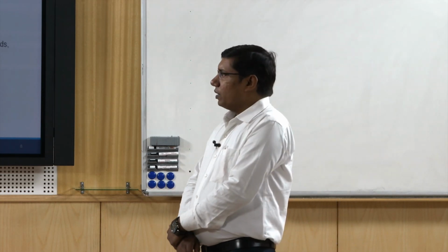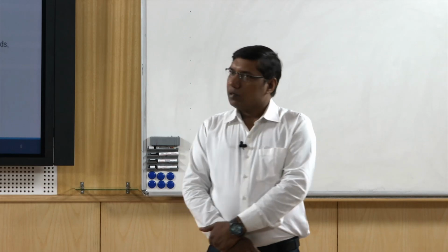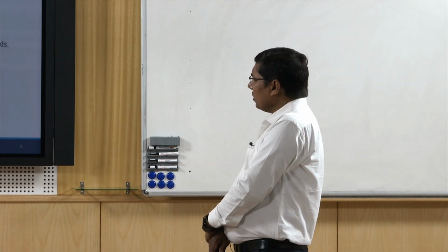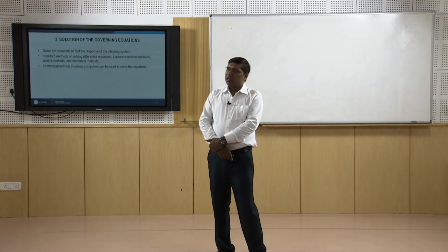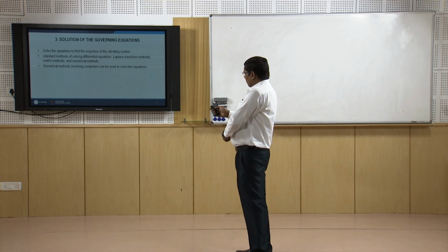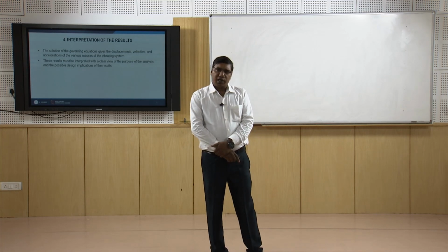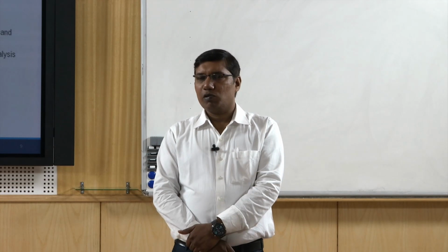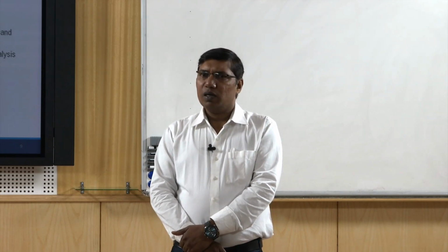So, in case of nonlinear systems, numerical methods are more helpful because of the added complexity in the system. So, using these methods and numerical methods, we can solve our differential equations, and then we get the results. So, results, as I said, is in the form of the response of the system. It could be displacement response, displacement time plot, velocity time plot or acceleration time plot.